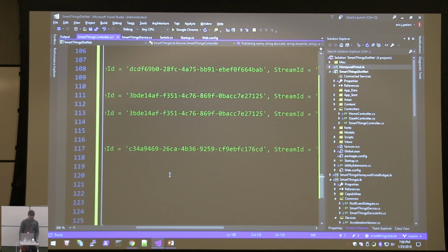Well, does the app actually know that the switch is off, or does it just think the switch is off? It will know that the switch is off. It will know that I turned it off, and it'll show the correct state in the SmartThings app or in the code, but it won't fire any of the events. So it's a hole, I think. I'm kind of surprised, and that might be a firmware thing with these guys. I'm not sure where the hole is. It might work fine with other devices.